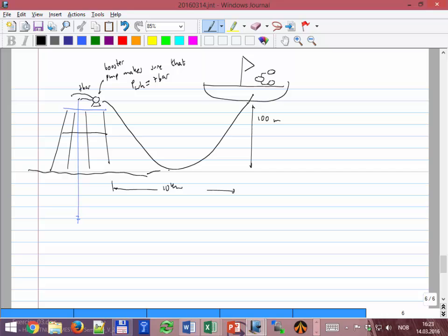Those questions are important. You all the time have to relate, and a good way to see very quickly is to say, okay, 100 meters is like 10 bar for water, and that really is quite a high distance, so there is something wrong here.